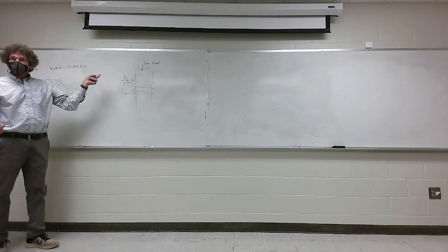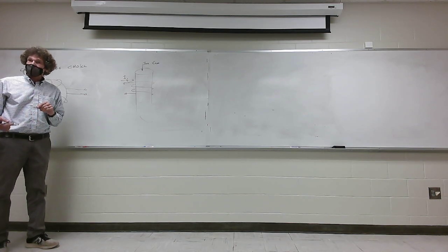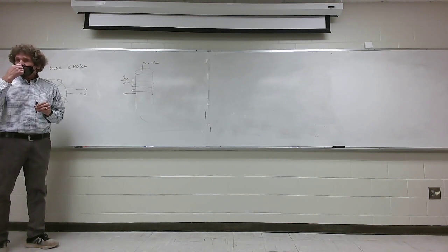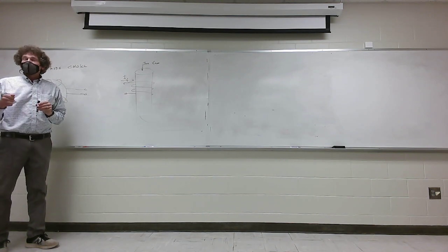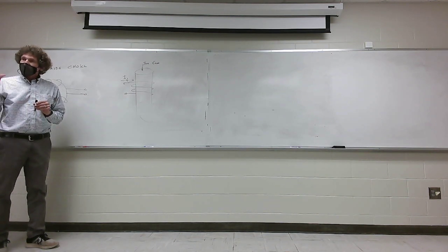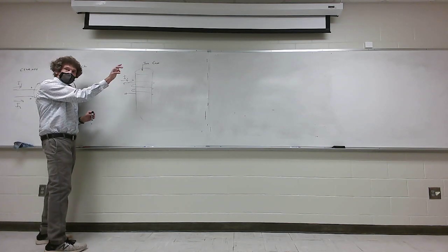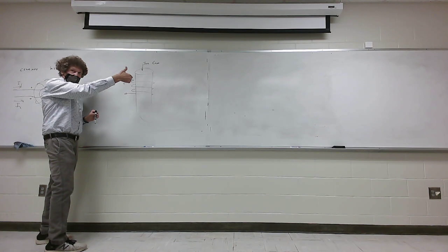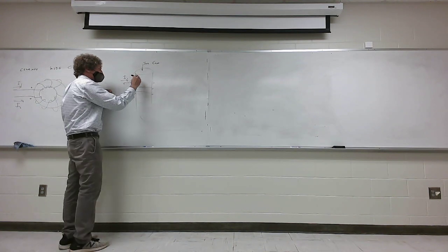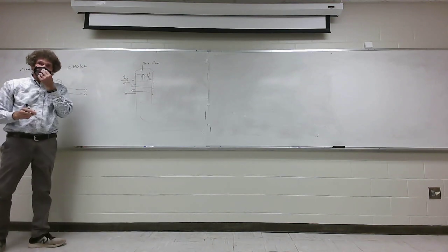First thing is, if current's going in there, which is the direction of the magnetic flux based on your understanding of either physics or engineering? How can you know? You're right, but how do you know? Because you all have right hands, I hope. Well, if you take your right hand and take your index finger, put it in the direction of current, and wrap it around that thing, your thumb on your right hand points in the direction of the flux. That's magnetic flux. That's it.